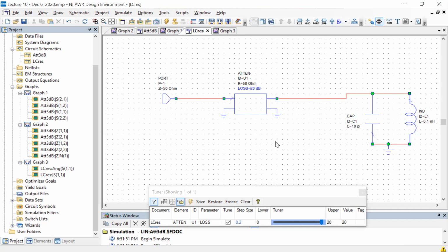Yeah, makes sense. And I guess in the case of S11 and S22, you don't need wires to connect it. That's why it didn't pose a problem. In case of what? So you said that for S11 and S22 you can't really use this background data divided by memory. Yeah. And I guess he needed wires in the practical sense to connect two different ports to the VNA. Whereas for S11 and S22, you just need to connect one port and sort of match all the others to 50 ohm. So yes, that's probably true.